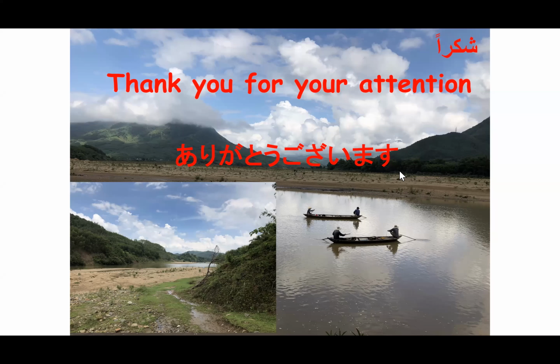Okay, so it is very important, of course, but it should be considered how much sediment is coming from the upstream, and then how much flow of water or rainfall runoff, and then you can easily design your dams, which you call gabion dams.